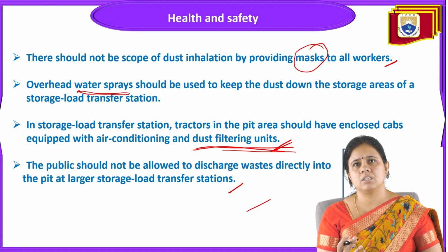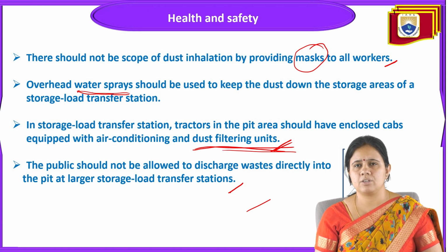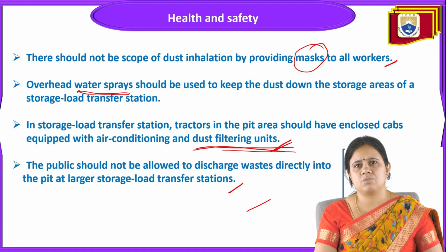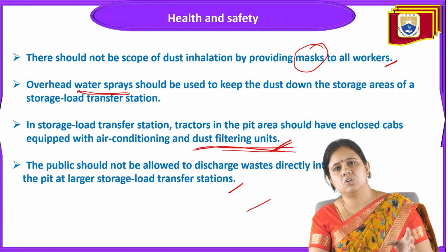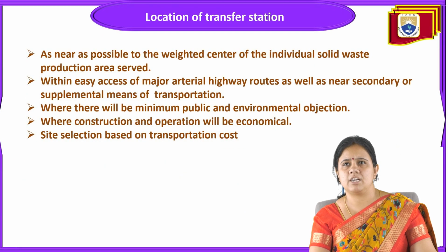So first of all, there should be no scope of dust inhalation. To avoid dust inhalation of the workers, masks should be provided. Overhead water spray should be used to keep the dust down at the storage area. In a storage load transfer station, tractors in the pit area should have an enclosed cab equipped with air conditioning and a dust filtering unit. The public should not be allowed to discharge waste directly into the pit at a larger storage load transfer station.